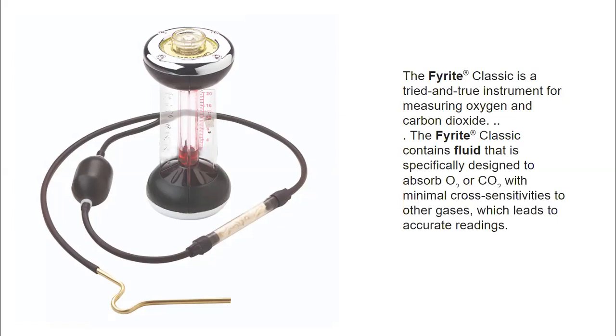So this instrument can also be used as a substitute because this would obviously be a cheaper instrument, and if you don't want to use a costlier combustion analyzer, one can also comment and do the calculations on the boiler system by using this Fyrite instrument. What is the principle I told you?